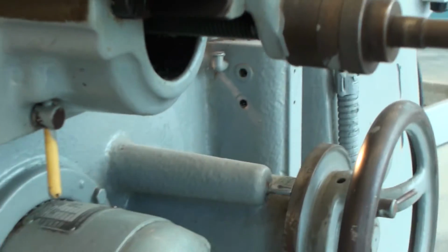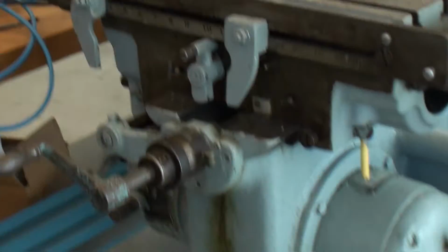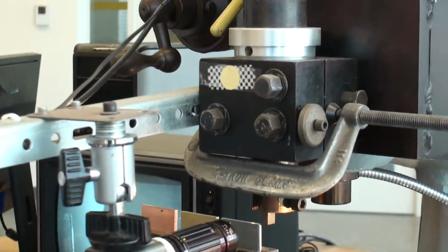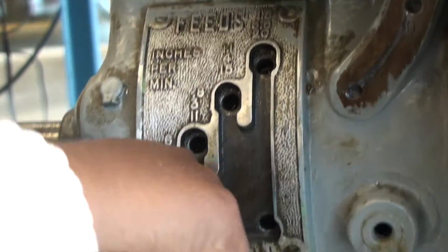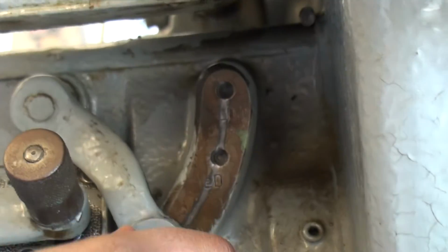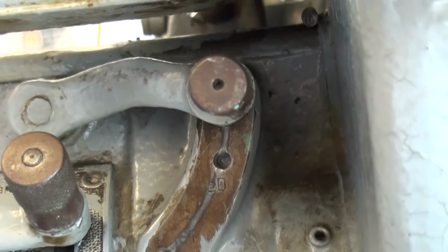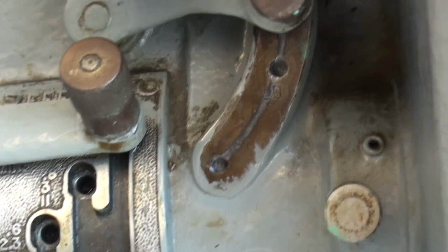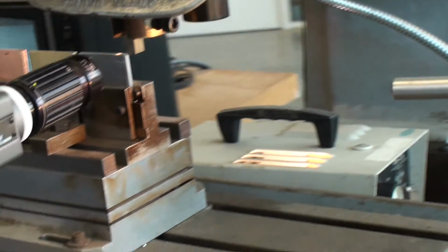And now we need to adjust the machine so that we can have our feed rate of 1.5. Okay, so 1.5 is all the way up here. First things first, we want to bring this part up here. And this is already at the slower speed, so we're already at 1.5 there. Okay, so now we're going to start cutting again at the beginning of our material.